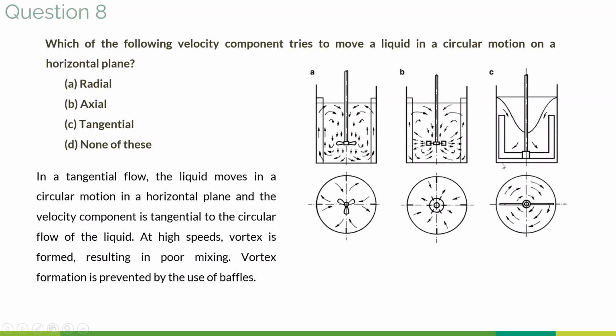And that is something you don't want, because you need to make sure that all the solid particles are being mixed completely instead of being accumulated at one end. Apart from this non-homogeneous mixing, you will see that a large portion of your shaft is exposed to air instead of the liquid, which means that the majority of the power that you're supplying to rotate this impeller is going to waste, because it is not even in contact with the liquid, it is in contact with air. So both for power requirements and because you're not mixing the components properly, vortex formation is not preferred in a system.